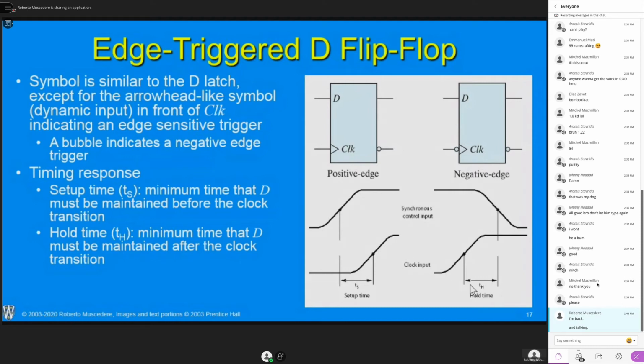The hold time works a little bit opposite, I suppose. How long do you have to keep the clock at a particular value for the flip-flop to grab onto the data? So if my clock is switching too quickly, and I'm out of spec of the device, chances are I may not be able to catch that data in the first place. So we have to be very careful about that.